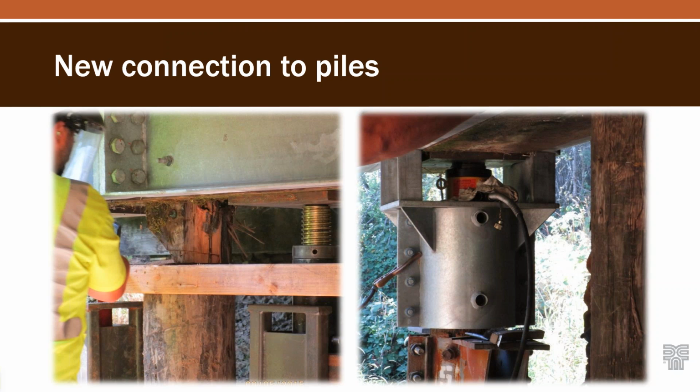And then there's kind of like a timber pile repair. There's a concrete collar, that's that steel encasement going around the pile to make that fixed, and then channels, shims that are welded to the channel that's on the cap up above. And so now you've completely replaced the load path from the timber. So this was an in-place repair that was done.